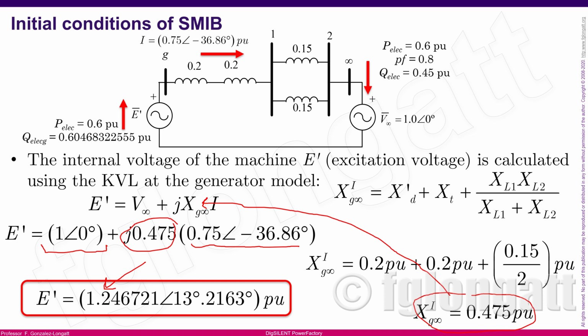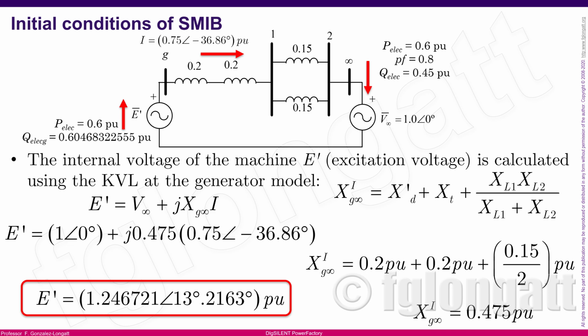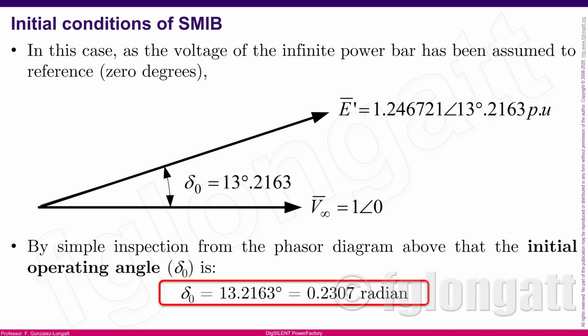Using this basic ideal model, okay? What we need to do now is, if you remember, we assume that the voltage of the infinity bus bar is the reference, and that is a typical case, okay? Because typically we assume that the infinity bus bar is so large that the angle can be the reference and it's not moving, there is no change in frequency, there is no change in position. That is the infinity bus bar concept, okay?